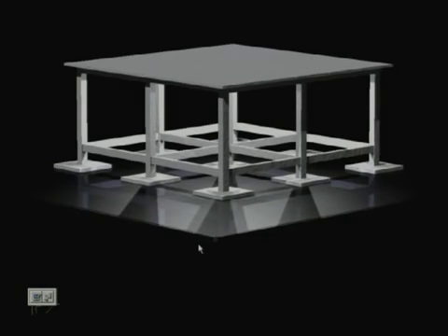We start construction from the bottom, but when we design, we do it the other way, starting from the top: slab, then beam, then column, then tie, then footing. Even if you have a staircase, the staircase has to be designed first. So this is just one schematic.